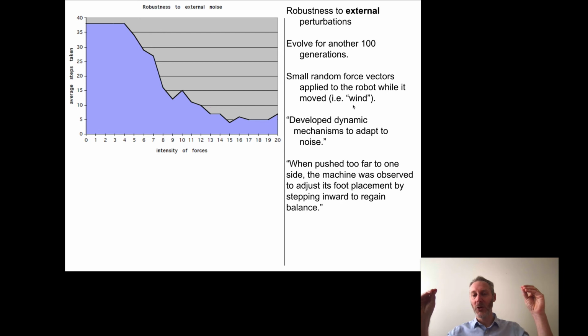So now, as the robot is walking on flat ground, they apply very small, random external forces, and they attach them to the body. Remember that at heart, at the lowest level of the physics engine is the equation F equals ma, and if we rearrange that, we get A equals F divided by m. We can arbitrarily add in whatever forces we want to the physics engine. Here they're adding external forces that are going to tap on the different parts that make up the robot's body.